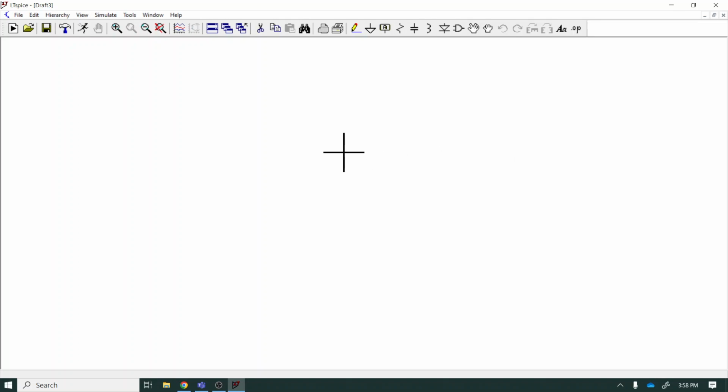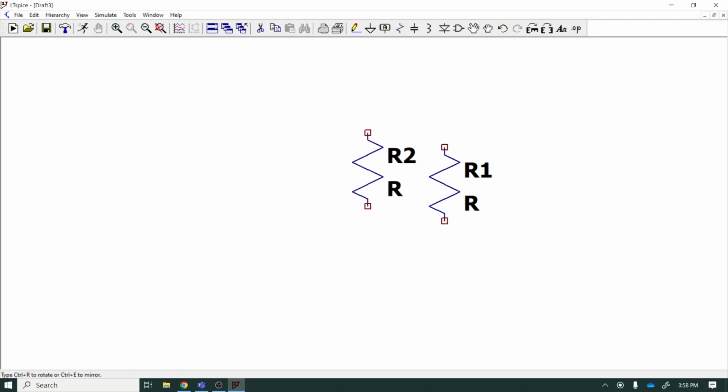So I want to go straight in and start by just creating a really simple circuit. So I'm just going to do a resistor and a power source. So up at the top here, you have resistors, capacitors, inductors. The resistor is right here. I'm going to take a resistor. I'm going to stick it on my screen. That's a single click. Once you're in the sort of resistor placing mode, you can see my cursor has turned into a resistor. Anywhere you click, you're going to drop a resistor. We only want one for this, so press escape to go back to sort of the crosshair mode.